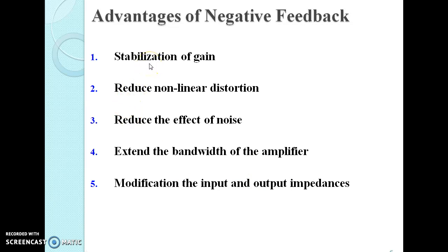Now, what is stabilization of the gain? It means that it makes the gain less sensitive to the changes in the circuit components due to the changes in temperature. The reduction in non-linear distortion makes the output proportional to the input, keeping the gain constant independent of the signal level. The reduction in the effect of noise minimizes the contribution to the output of unwanted signals generated in the circuit components or interference.